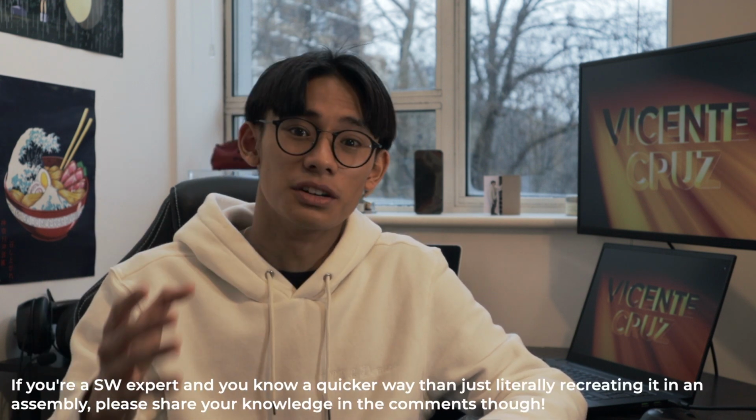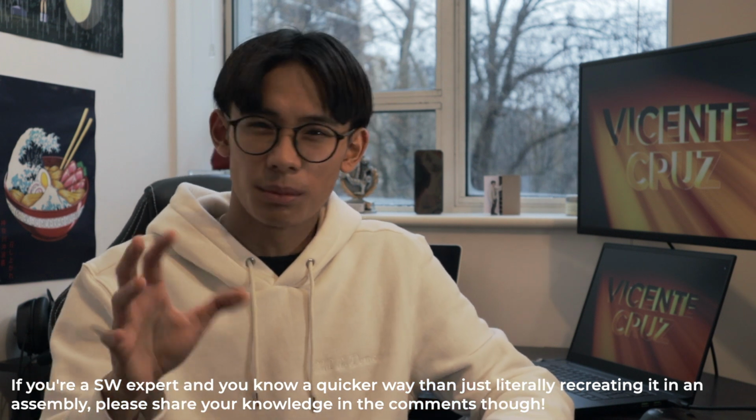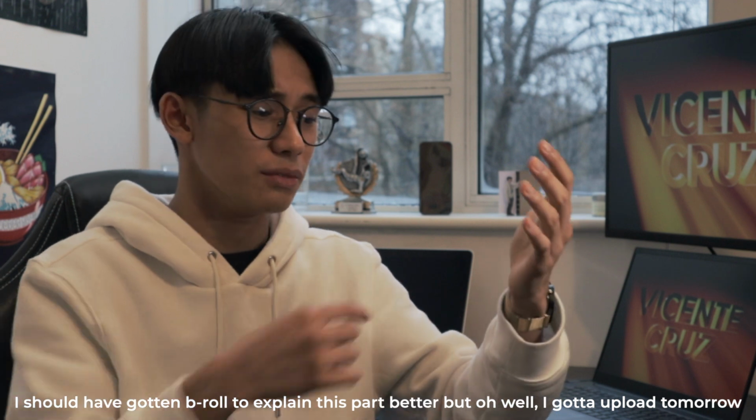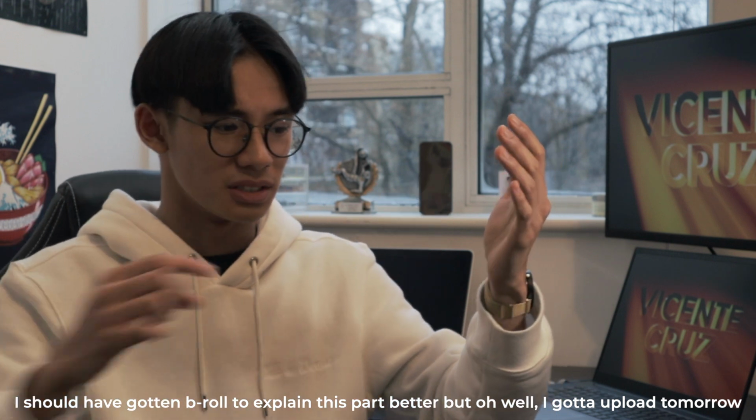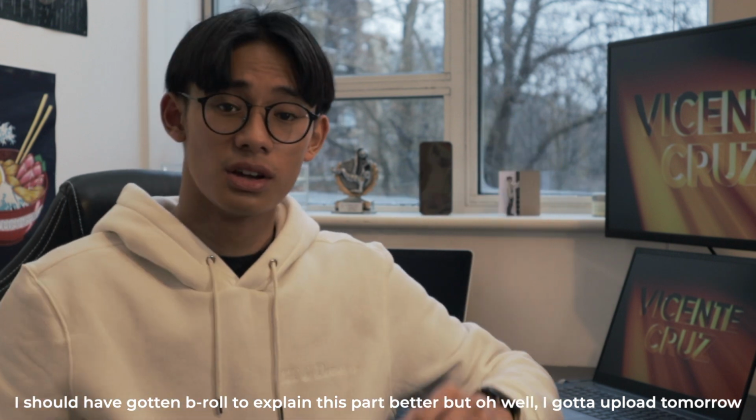Probably a more experienced SolidWorks user who's watching this right now is kind of scratching their head at the stupidity of my process. However, I'm kind of hoping that I was pretty efficient. One great tip I learned was the convert entities command. So I could basically just reference holes in one body and reference the positioning onto another one instead of having to use my slow method of smart dimensioning both things to a certain length. So yeah, thank you, Tiernan.